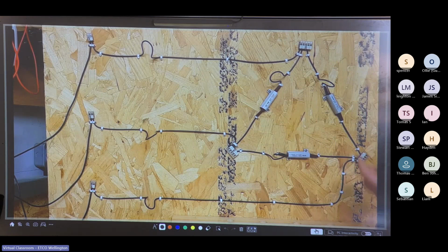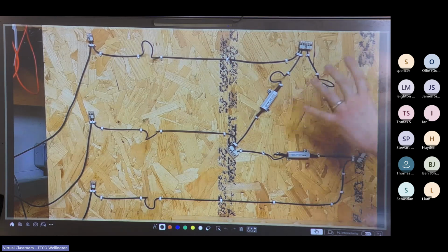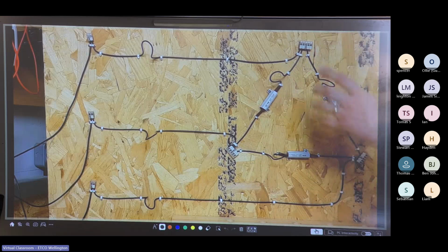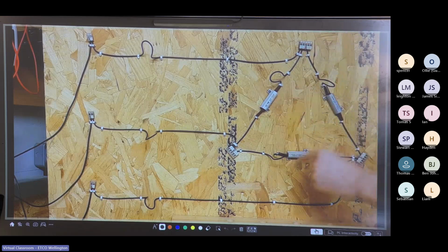But it's very important to bear in mind that if you open up something like a transformer or a motor that has a delta connection inside it, it won't be physically laid out as a triangle. The loads will likely just be side by side or perhaps arranged around the frame of a motor. And it is the way that we connect the ends of the loads together that makes it a delta connection.